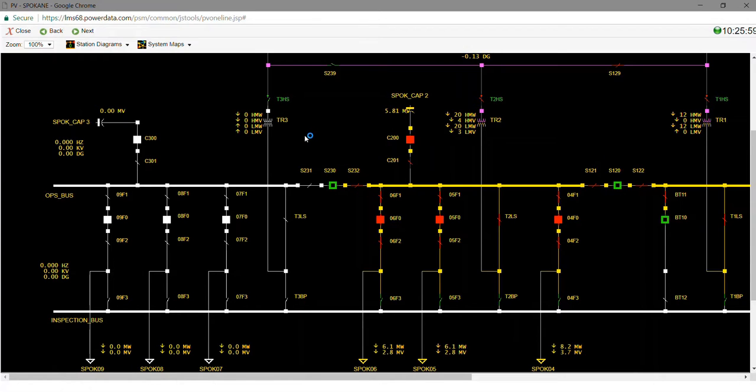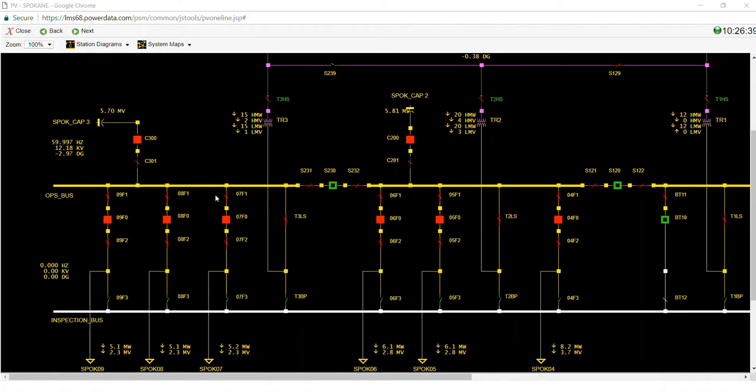A load break switch functions just the same as a circuit breaker. Now in reality, even load break switches have very different sets of parameters. Some are only rated to, let's say, de-energize a line. So just remember that while you have a little more freedom with what these switches can do in the simulator, it may not be the same in the real world. With my non-load break switches, in order to operate those, either both sides of the switch must be de-energized, or you have to have a parallel path or some kind of operation where you're not making or breaking any current. It's not going to cause any kind of flow across